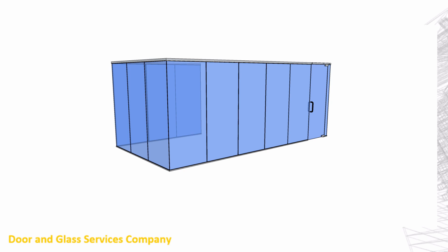But without really getting into the weeds and trying to optimize the design on every single project, it's a couple of screws. We expect that we're going to be good when we get into an interior space and we anchor these systems at 24 inches on center with 1/4 inch diameter fasteners, which should always be countersunk.